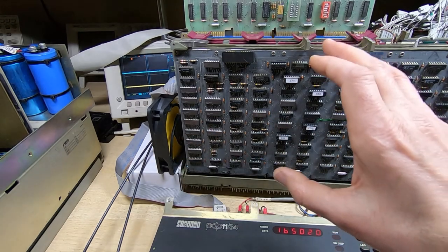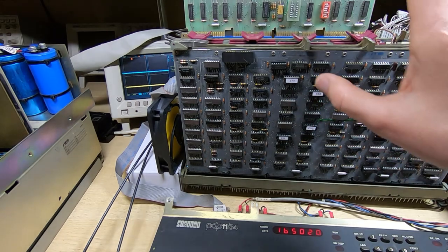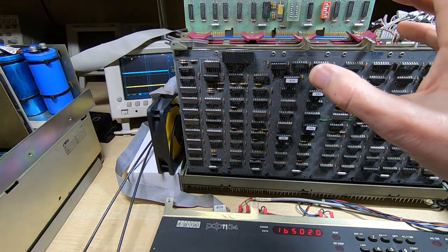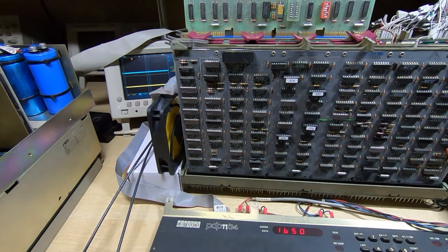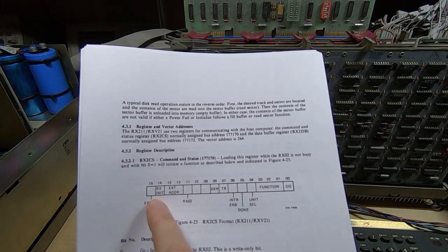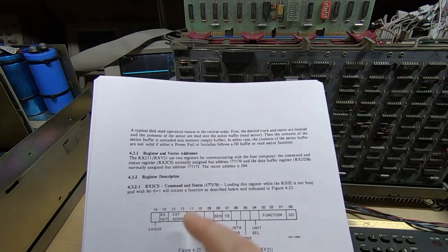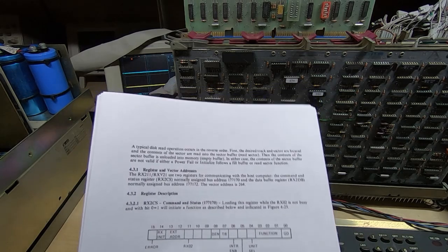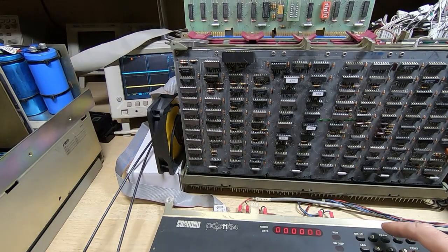What we want to do here is see if the system is capable of accepting commands through the interface card, whether it can successfully send those commands through to the drive, and if the drive will respond. So we'll start by setting just that 1 bit, and we'll send that to the drive through the interface, and we'll see if the drive actually resets. So we need to select the correct address. As I said, that's 777170, and we'll set just that 1 bit, which is a value of 40,000 octal. Send this, and if this works, then the drive should reset.